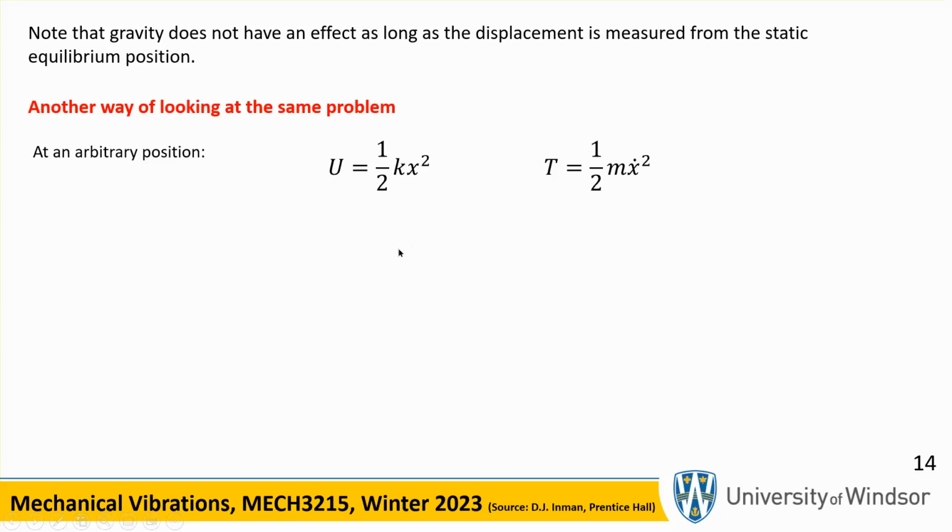In other words, if you measure from that equilibrium position, that red line, you move the mass down below by the amount x. This is how much the spring is going to be stretched from the equilibrium position, and the amount of energy stored in the potential energy is 1/2 k x squared. Now you can add them up and say it's constant and differentiate it.